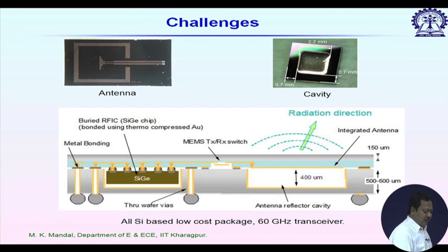For example, this antenna is a resonating structure, it has some fringing electric field in silicon and air. So, it can interact with other metallic parts of the chip itself. So, the antenna should be placed as far as possible from the chip. Not only that, if there is any metal part on this chip itself, then we have to use some sort of insulator in between antenna and the chip part, or simply increase the separation between antenna and this chip part.